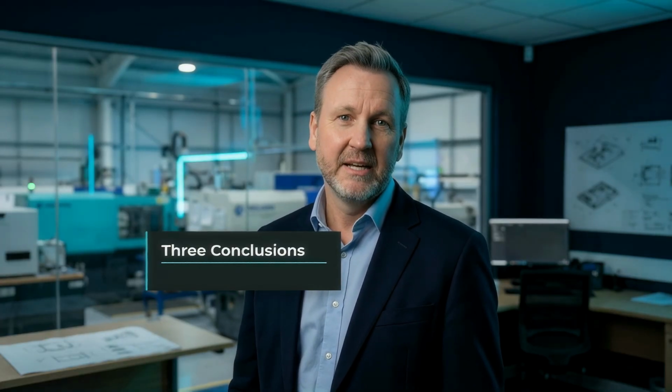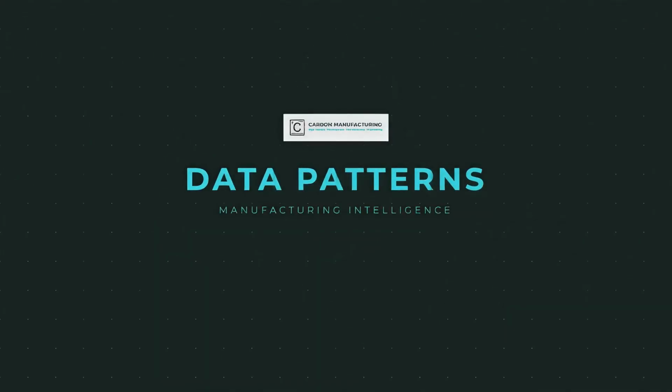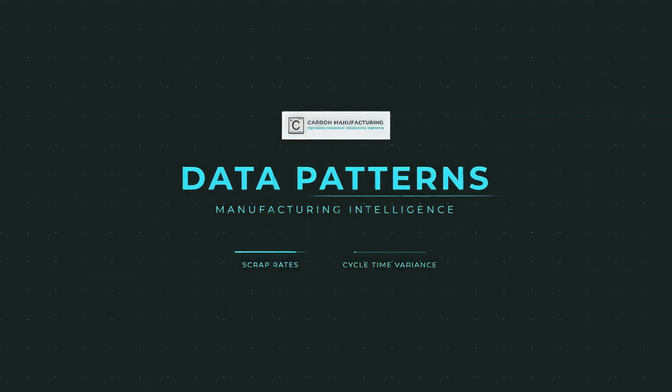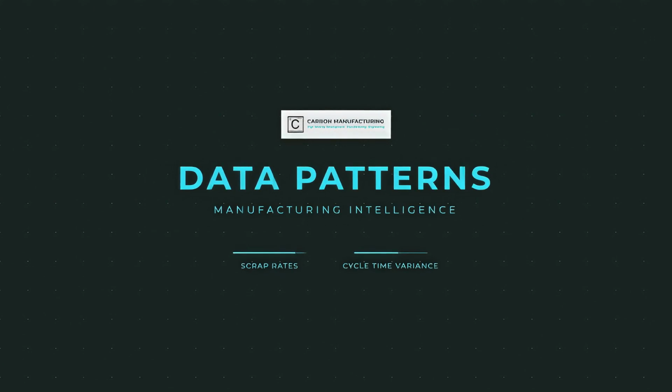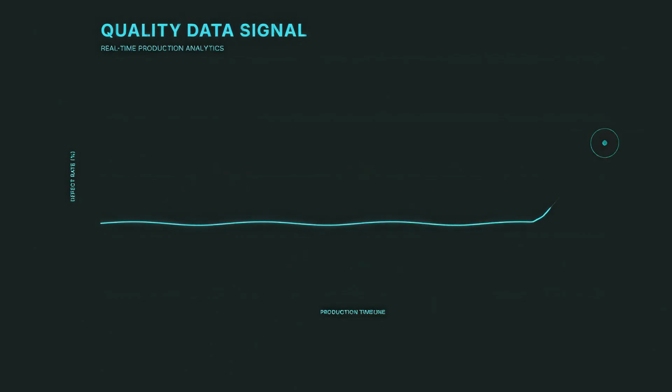So what does good look like? Here are 3 conclusions I've come to after 20 years of running these systems. Number 1, data is your most valuable asset. With AI now able to find patterns that humans cannot see at scale, what you document matters more than ever. Document everything, scrap rates, cycle time variance, and pay special attention to quality indicators because they are the canary in the coal mine. A defect uptick in week 3 is telling you something is wrong. If you're not feeding your AI and analytics tools with rich, consistent quality data, you are leaving the most valuable signal in your operation on the floor.